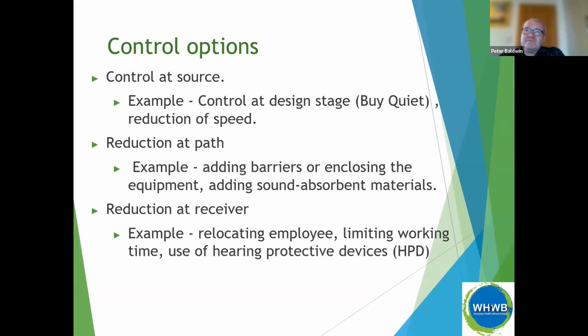You will find that machinery comes with details of how much noise it will be expected to make. So as time goes by, you can just replace the machines with quieter machines. Reducing the speed of the machine can have quite a large effect on the actual noise levels. And then there are subtle things like on saws, you can get low noise saws, and they have an S-shaped cut into the actual saw blade itself on the big circular saws. A little less cut in there does significantly reduce noise.